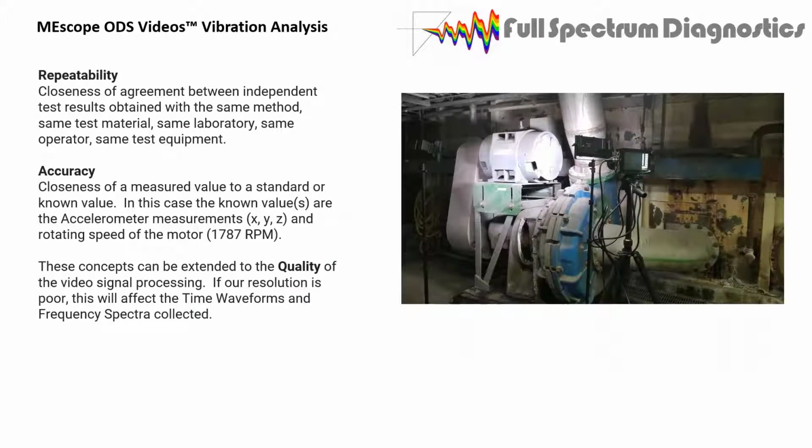All right, we have one other aspect of this, and I have my repeatability, I have my accuracy, and we kind of covered those as much as we can. I want to extend that to the quality of the video processing. If our resolution is poor, this is going to affect the time waveform and the frequency spectrum. So we want to make sure that we get some of the setup parameters right before we go in and start processing data. Okay, and I have a good example of how that works.